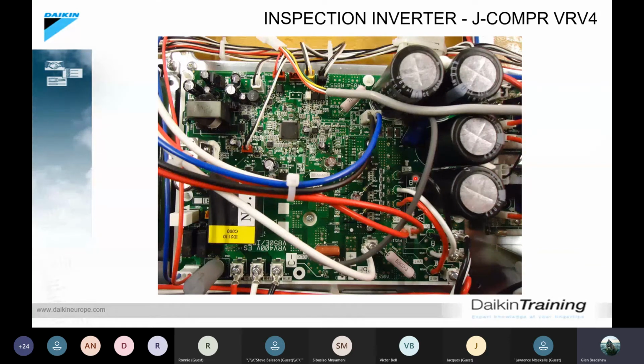It's recommended that when you do your 1000-volt tests on a motor, you hold that down or use the lock function on your megger and do at least a 3 to 5 minute test to see if there's any breakdown in the insulation. We've seen results where guys will do just a simple pulse test, and when you hold the voltage down through the lock button, you will see the fault come to light when they're down to earth, where you'll see a winding that's shorted or something.